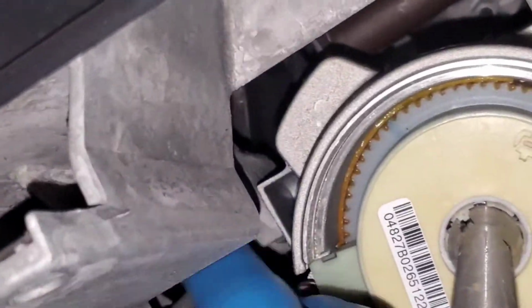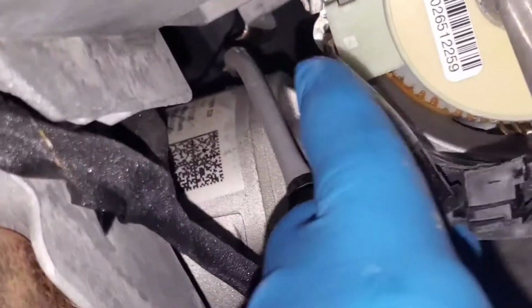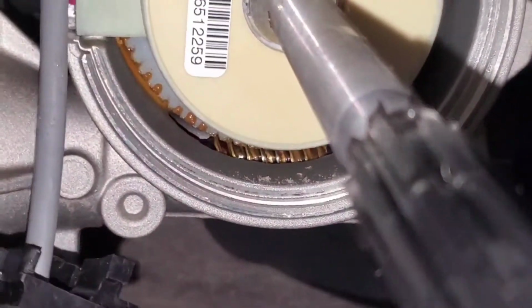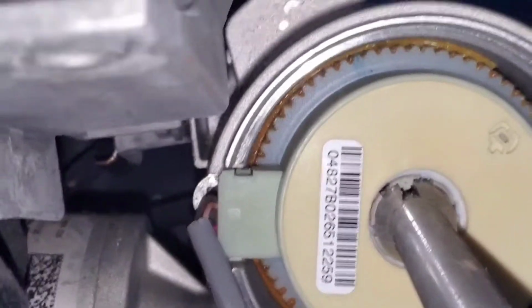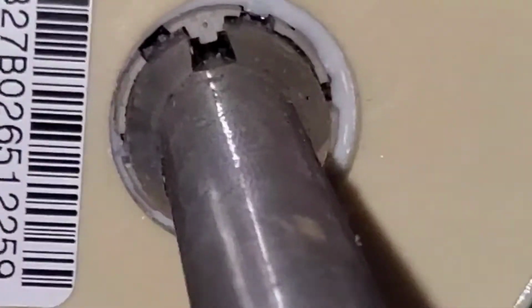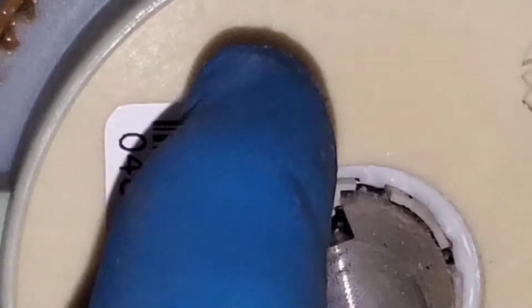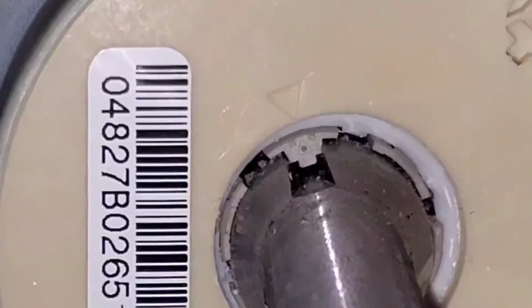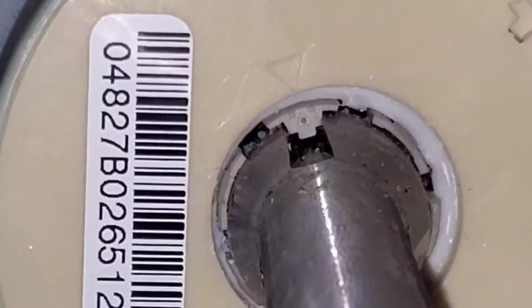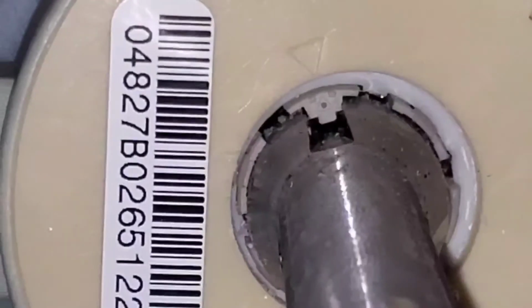And the moment of truth, I've pulled the connector out of the side of the motor there. All right, here's the part that we kind of don't want to mess with here. It's very important that this thing is indexed right. So I'll show you guys what I mean. This slot on the shaft and that arrow have to line up. It typically only goes one way, but that's probably where we're at.